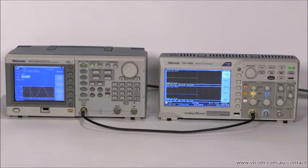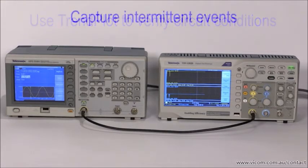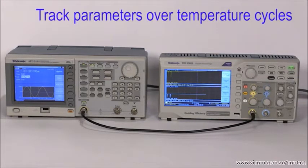The TrendPlot function is especially useful when you need to record measurement results under a variety of test conditions. For example, you can use the TrendPlot function to verify circuit design specifications, or to capture intermittent events, or even to troubleshoot random shutdowns. You can also use it to monitor a power supply during temperature changes.